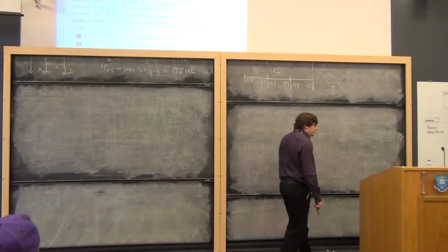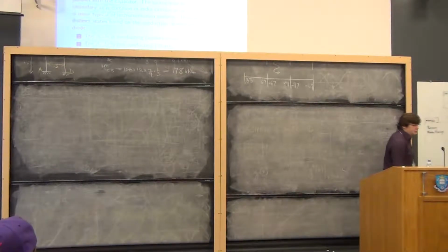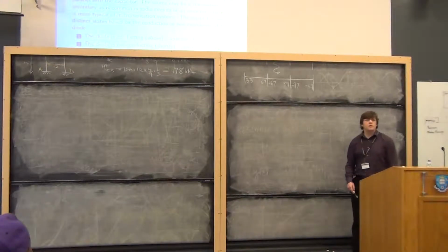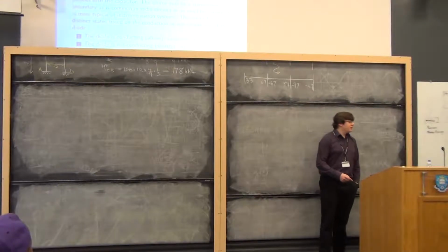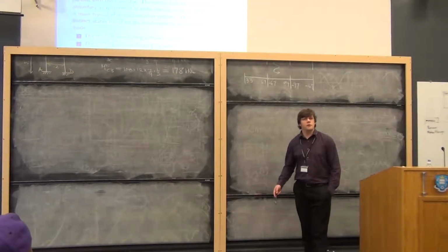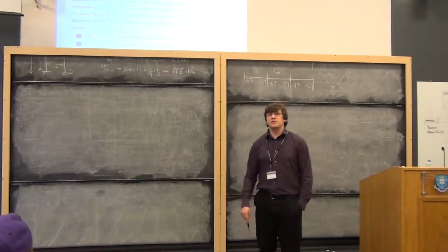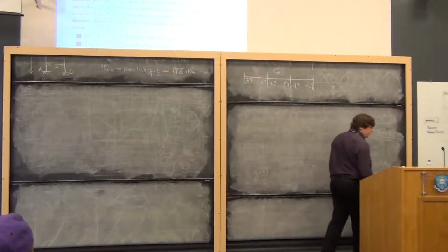And what about the resistor? Well, in this situation, the resistor will dissipate some power and some current will flow through it, and that current will be supplied by V1. Because, well, you could say the current will come out of C1, or the charge will leave C1, and it'll be a current that will flow through R1, and that charge will be replenished by V1. But it's much easier just to say, well, V1 supplies the charge. It's the same thing, more or less.